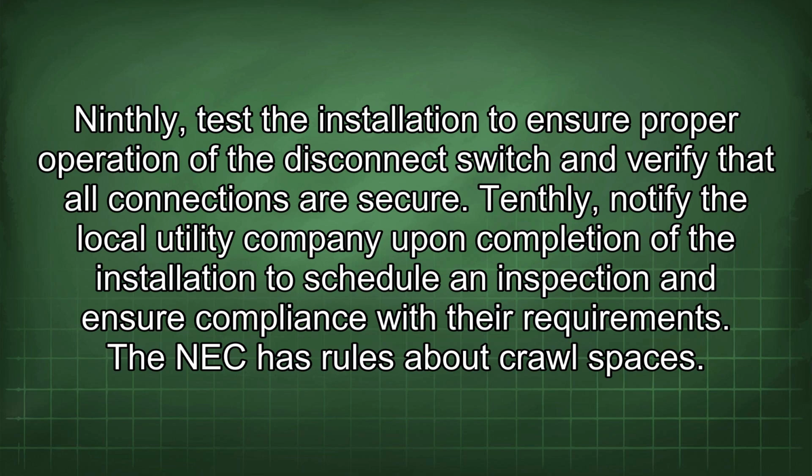Ninthly, test the installation to ensure proper operation of the disconnect switch and verify that all connections are secure. Tenthly, notify the local utility company upon completion of the installation to schedule an inspection and ensure compliance with their requirements. The NEC has rules about crawl spaces.